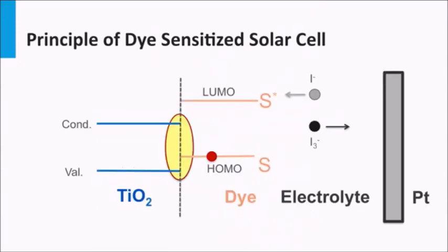Let's consider first the photoactive parts of the solar cell, which consist of the photoactive dye sensitizer, which acts like an electron donor. The second material is the titanium oxide nanoparticles, which act like the electron acceptor. The dye material is mixed with titanium oxide material like in organic bulk heterojunction solar cells. The photoactive material is the so-called dye photosensitizer, ruthenium polypyridine.